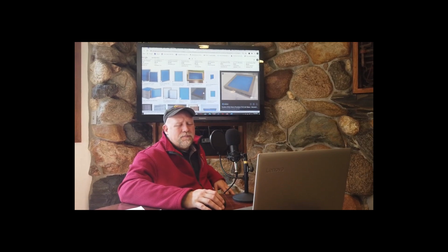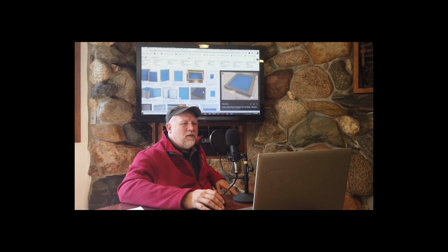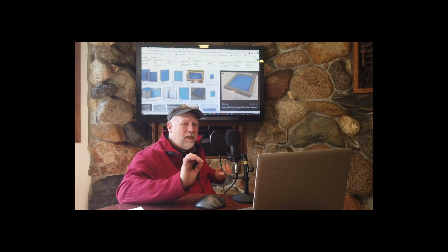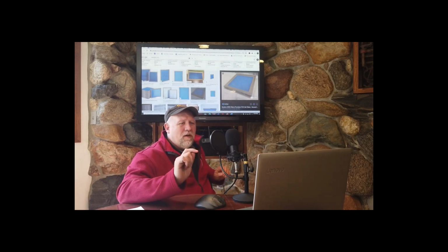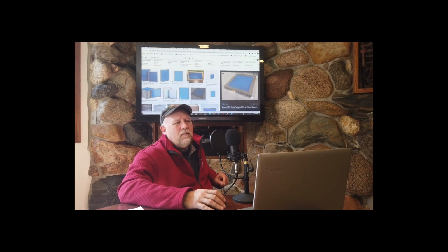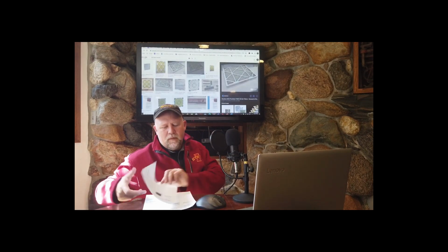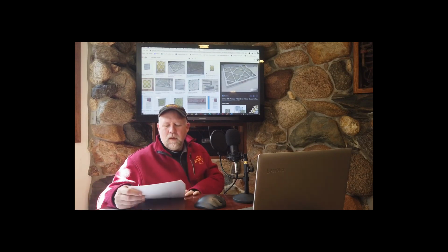These are best used as a pre-filter or not at all. They're kind of junk. They're not even a good residential filter. And notice 10 cents a square foot makes them cheap, and in filters, you get what you pay for. These are junk. All right, moving on. Let's look at a slightly better filter. On your handout, the Purolator FMEX 40, medium efficiency.